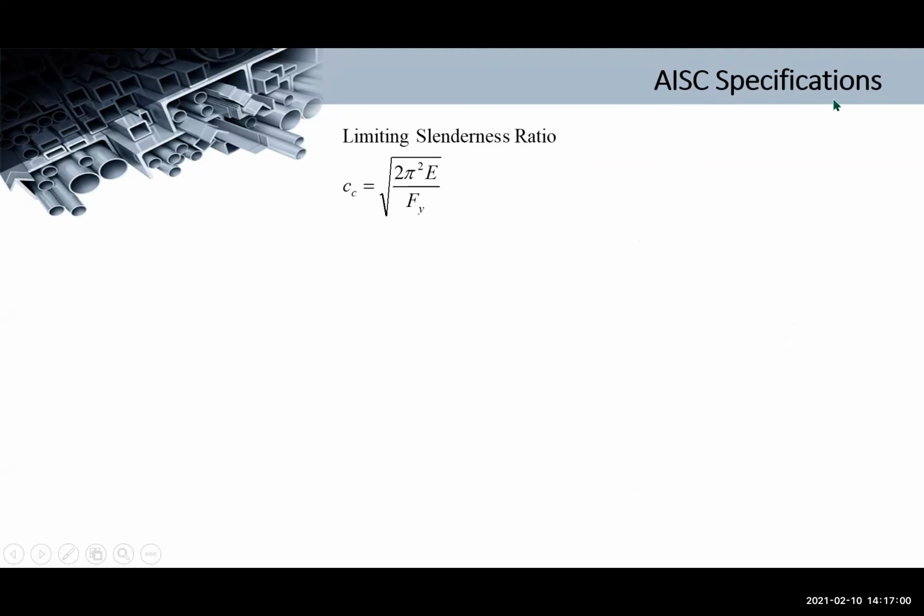And then this is under AISC specifications. Actually, in the NSCP 2015, we also have your LRFD and ASD. Again, the only difference is in the multipliers or the nominal strength: you multiply for LRFD and then divide for ASD. But for this discussion, this is what we will use, not that one.